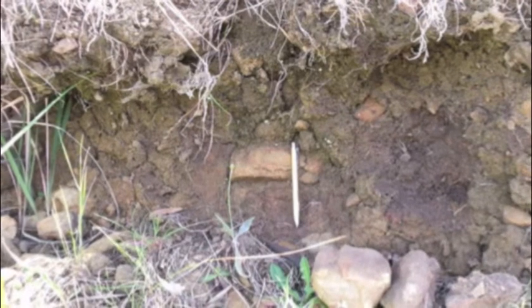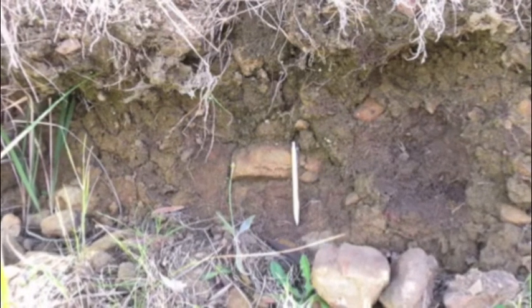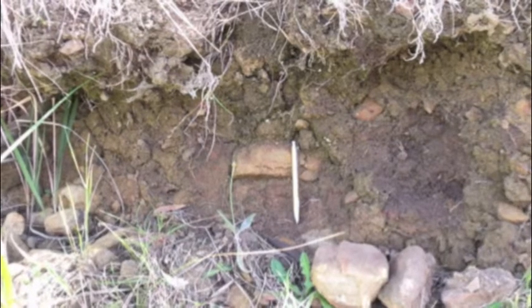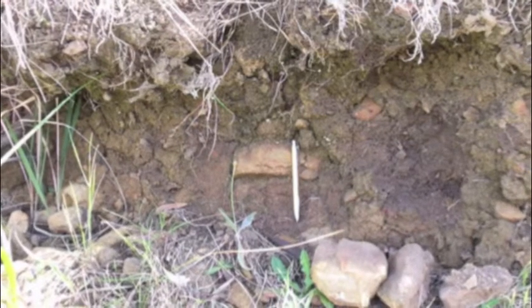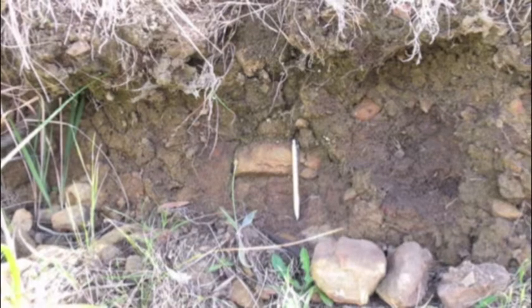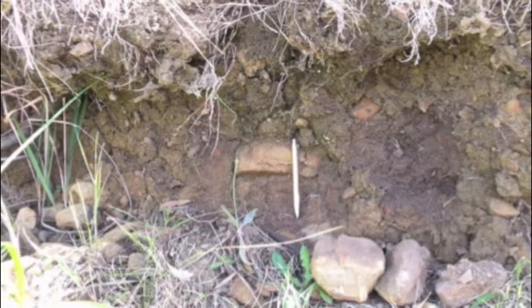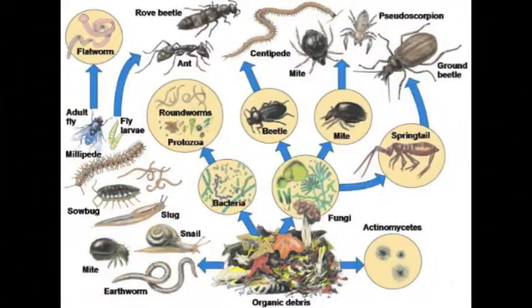For example, this soil profile at Wadi Wadi Track has a large A horizon and C horizon. The transition between rock and soil is very sharp, indicating a colluvium deposit. Soil biota break down organic matter and form pores and clusters in the soil.